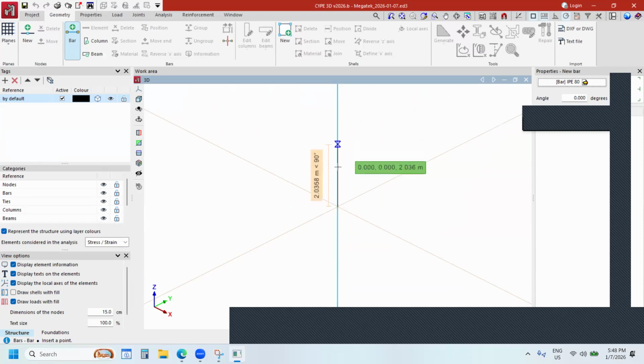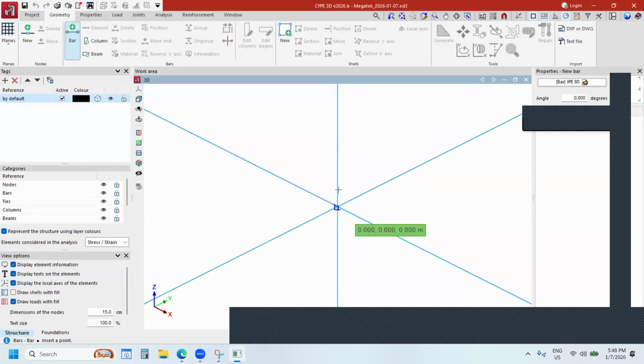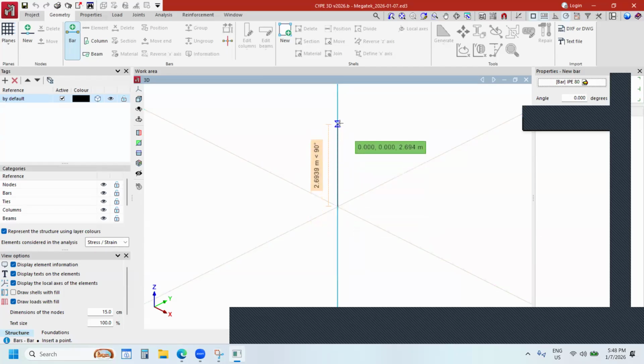But the thing is that we want to go vertically. So I'm not caring how far I'm going from this node, or intersect of these 3 lines. The only thing that is important for me is attaching to the Z reference line, or vertical reference line. Right now, for example, I'm going 3, and you just need a simple click.